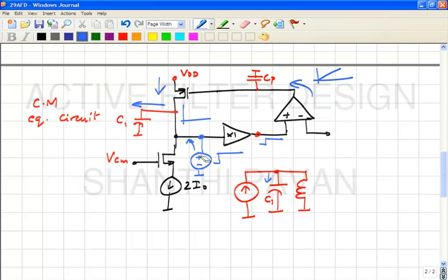Now, this step will cause this voltage to go how? Here it is held, but if somehow there was a step at this node, and how does this two integrator loop work? You assume there is some noise like step before, it results in a ramp. The ramp will get integrated and result in a parabola that's being fed back, and then that's the starting part of the oscillation. Okay, all right.